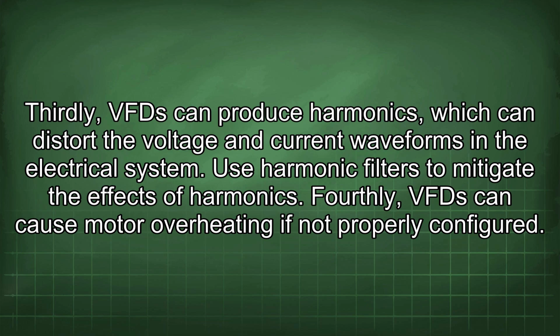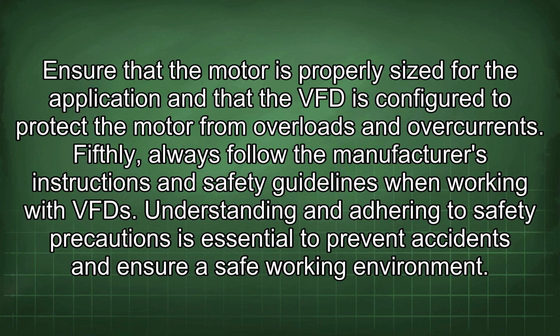Fourthly, VFDs can cause motor overheating if not properly configured. Ensure that the motor is properly sized for the application and that the VFD is configured to protect the motor from overloads and overcurrents. Fifthly, always follow the manufacturer's instructions and safety guidelines when working with VFDs. Understanding and adhering to safety precautions is essential to prevent accidents and ensure a safe working environment.